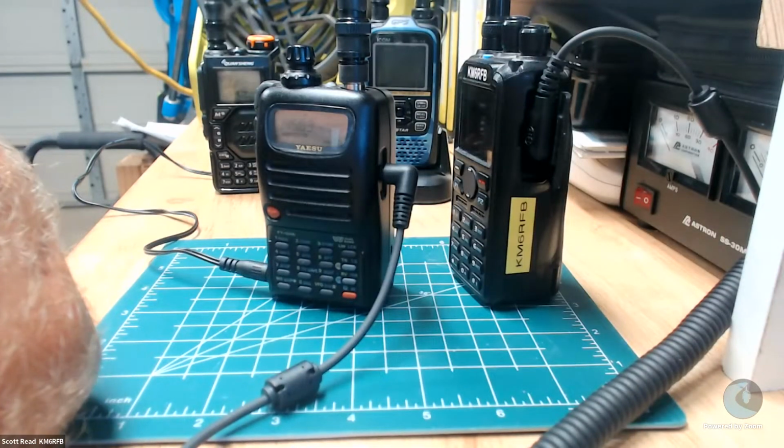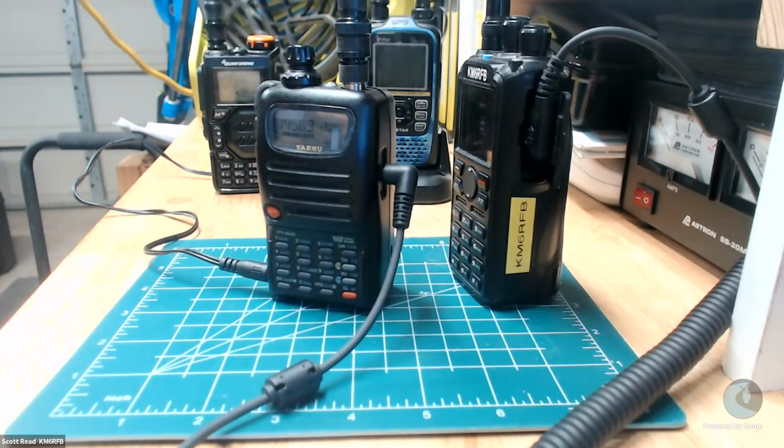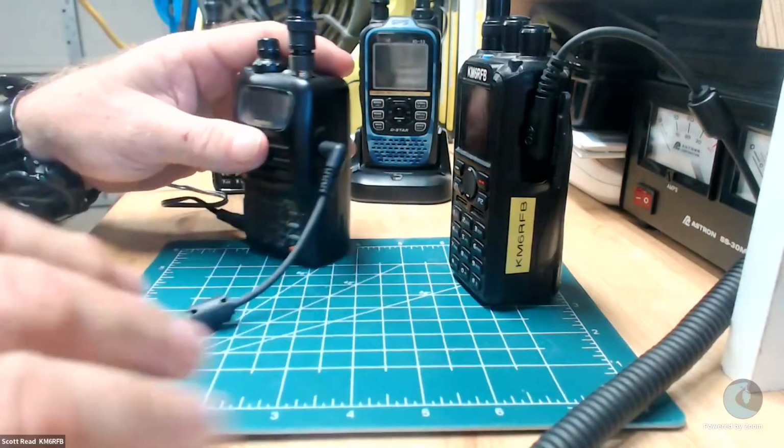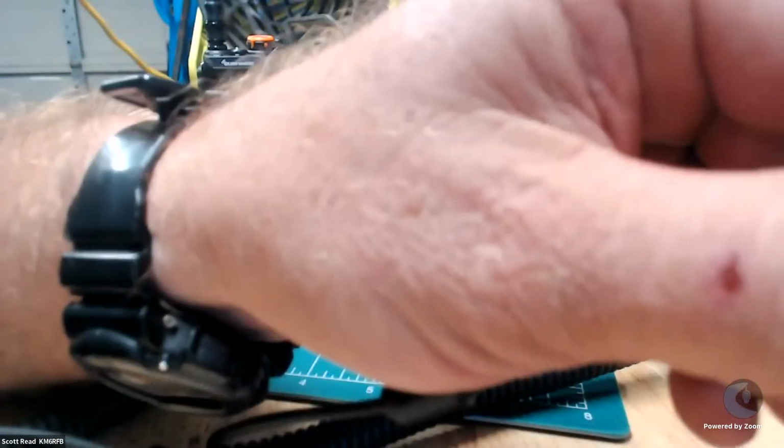Great, thanks a lot, Scott. Just one comment, Chris. Something I found on the Baofengs and Quansheng radios, it's really helpful to set your squelch level to 0 or maybe 1, but turning the squelch all the way down seems to solve a lot of problems. For sure. Because if you don't have the squelch set to the correct setting, it's going to ignore all of the audio that you're hearing.